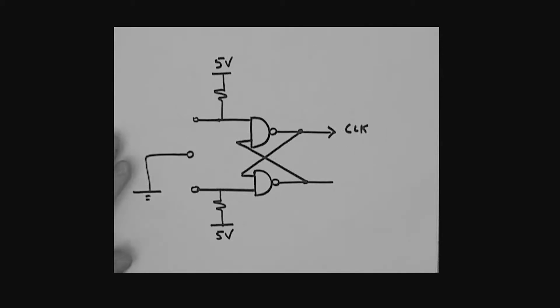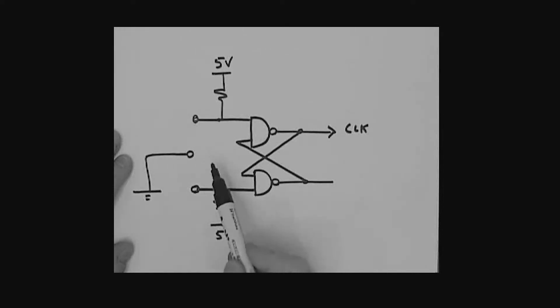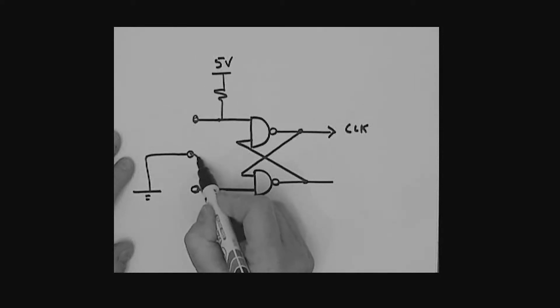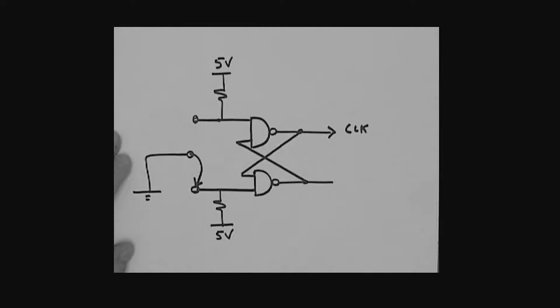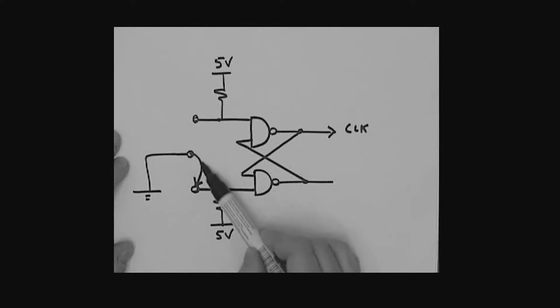Okay, so this is a circuit that could be used to solve that problem. This is a special kind of switch, very common of course. It's a single pole double throw switch. So we're going to imagine the switch is not pressed, and the switch connection is going to sit like this. We haven't pressed the switch at this point. When we press the switch, this connection would be from this point to this point. That's when we press it. When we release it, it goes from this point back down to here. Again, single pole double throw switches, very common.